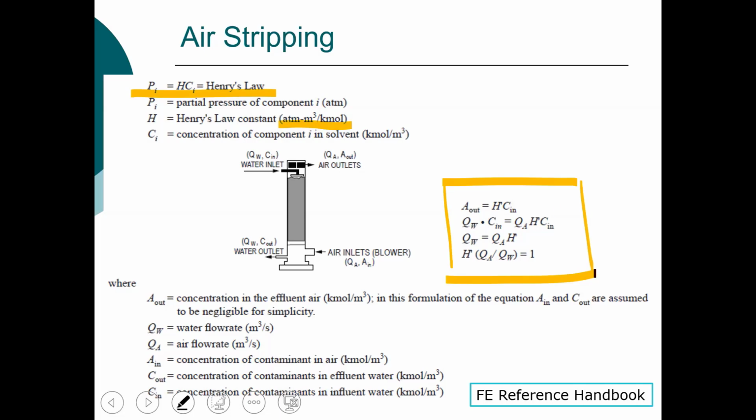Again, really what these here are all based on Henry's law. And we'll go through some of the terminology that's used here. Notice also that the concentrations are in kilomoles per meter cubed, so consistent with Henry's constant. And that's important to recognize that that's the case.